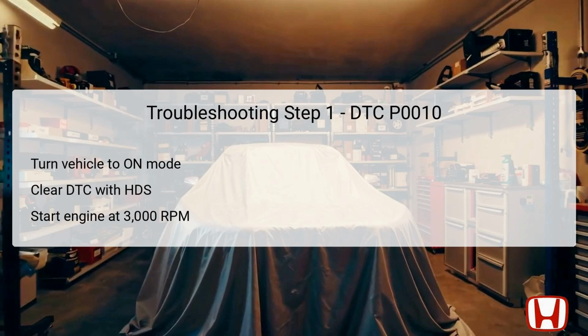This action must be performed until the radiator fan activates. Then allow the vehicle to idle. After these steps, check again for any pending or confirmed DTCs using the HDS. Confirming the DTC P0010 suggests that the problem persists, and the next troubleshooting steps must be taken.